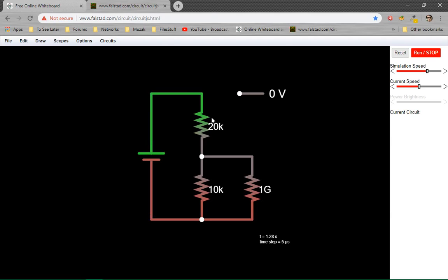So a way to simplify it is, first, we don't need a battery symbol. We already know that if our circuit works, it's most likely connected to some power supply. We imply that. We just put a label to say that we expect a constant voltage at that point. And likewise, we don't use this wire, or you don't even need this wire.